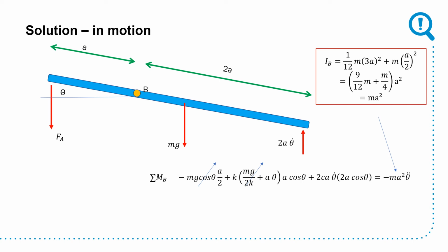So I've got to recognize the spring force. I've got to recognize the dashpot, the damper, and finally I am going to put negative for a reason so that I have the correct signs in my equation. So I'm going to assume that it's just sort of going like this. V for this system where the damper is acting, because it's a function of velocity, is going to be 2A theta dot. So that's where I'm getting all these terms.